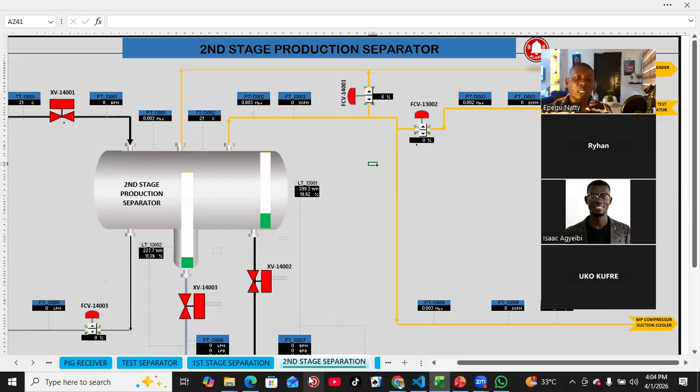They are also going to look at modalities, safeguards, right? If they bypass that alarm, what are the safeguards you have in case the level actually rises to the high alarm, right? Because what the transmitter is giving you is a false alarm, but what if the level actually rises to that high alarm, let's say about 90% and above? What's going to happen? What is going to safeguard the operation?